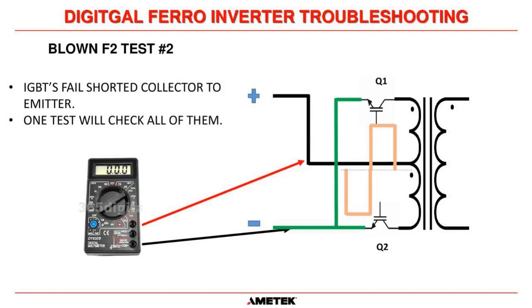Okay? In this case, if we see a shorted transistor, we do replace all the transistors here. And the reason is, at the time a transistor fails, there can be high voltage transients produced in here that could potentially damage a transistor but not show it as a shorted failure. I had to learn that the hard way.